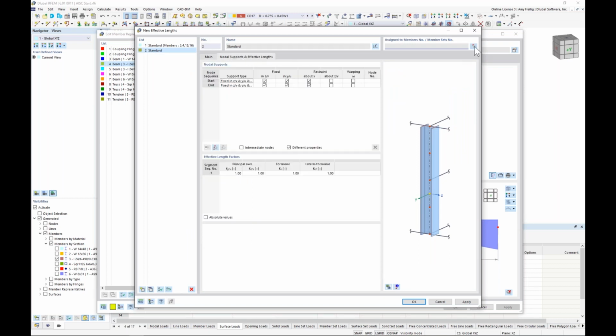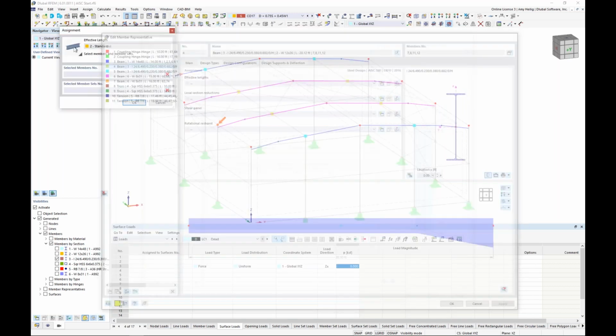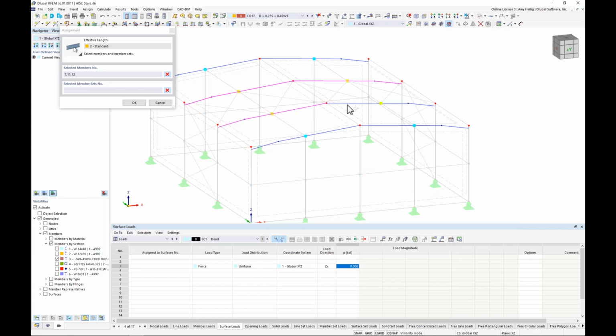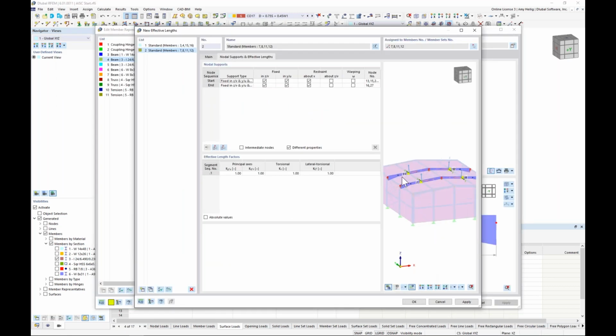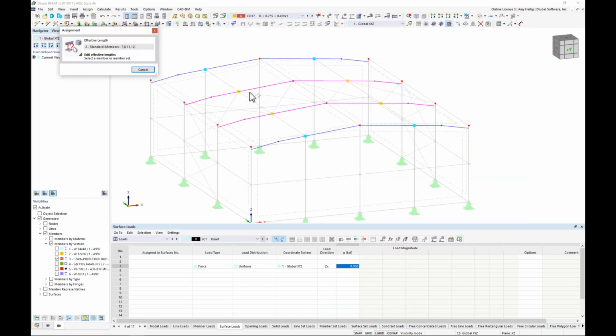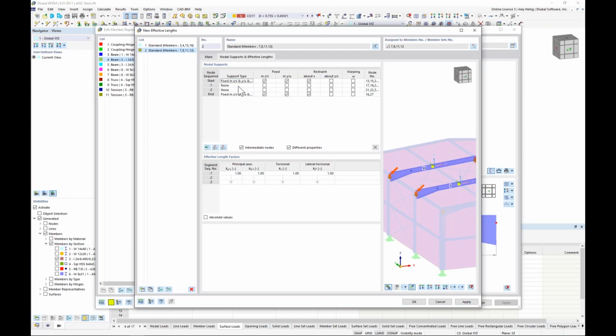And under the second tab, remember, again, I like to graphically select these. It's not necessary, but I think it's helpful in determining where you're at along the length of the member. So we're going to have the program automatically detect the intermediate nodes. 2 additional rows are given to us here. Now this is slightly different. The first node, we can leave as default.